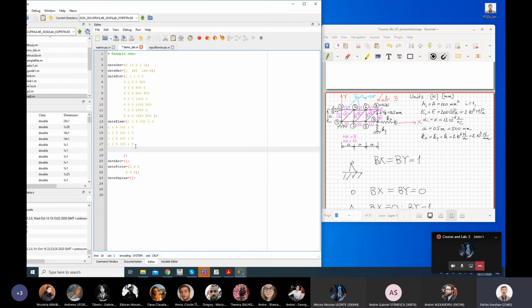Copy again. It's a little bit slow, you are younger and you will work quicker. So element number 1, let's put here element number 2, 3, 4, 5, 6, 7, 8, 9, 10, 11, 12, 13, and that's what I have, 13 elements. And let's modify the nodes. Element number 2 is 3, 5. Maybe 5, 3. Okay, it's the same, you can change if you want, not important. Element number 3 is 5, 7.